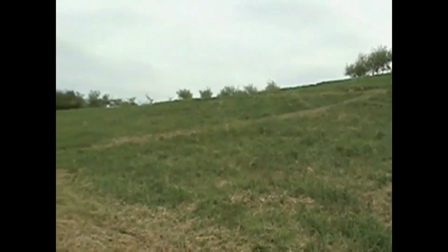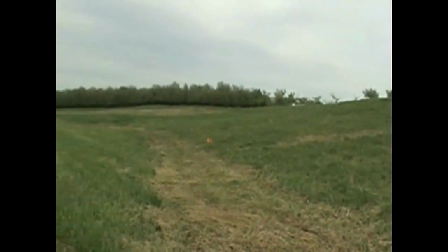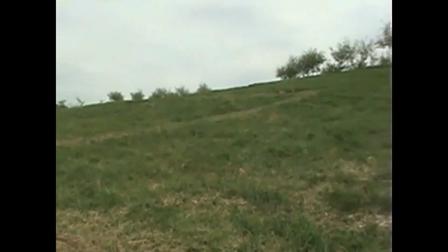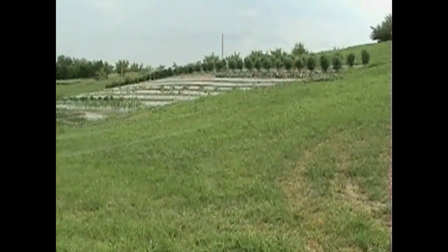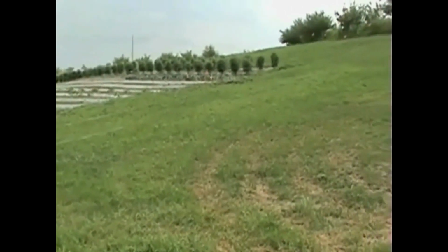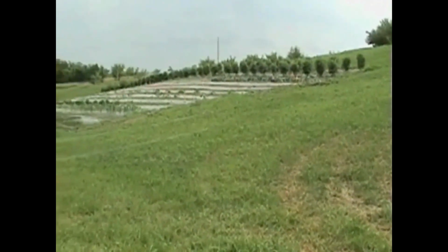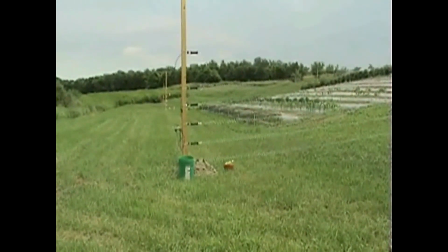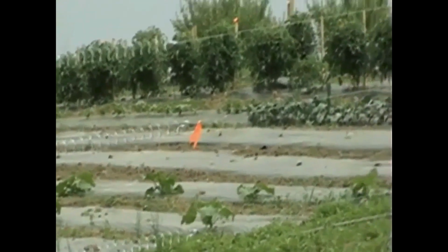Now, I'll tell you, if you really develop your skills, you can actually do that yourself without survey equipment. You get yourself a good 100 or 200 foot long tape and a good 25 or 35 foot tape and some pins, and you do some measurements correctly just to keep parallel, you can lay out anything you want pretty clean. But it's really nice to be able to stake out exact models very clean. And I'm sure you saw in the previous AutoCAD stuff how much detail and precision you can put into a map. And then we can stake any point on that map. Anything on that map can be staked exactly to precision on the land, as though you were painting the map on the landscape.